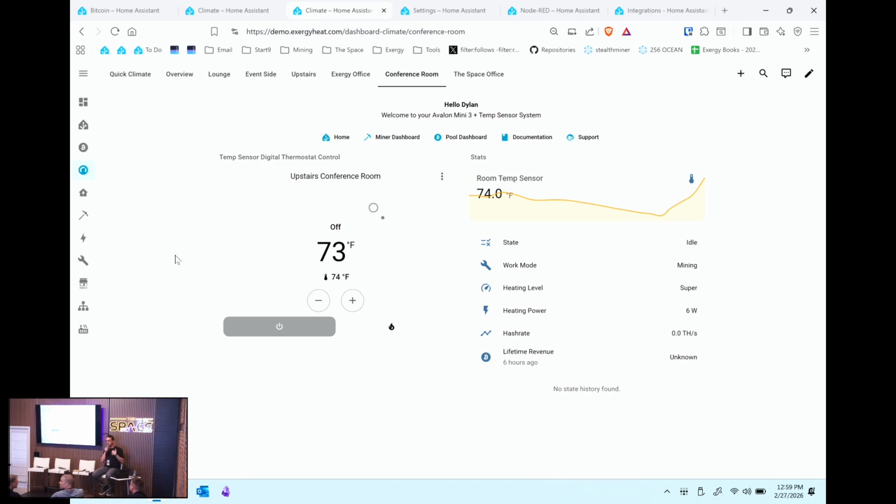Personally, I like to move away from Wi-Fi connected stuff, because if your router goes down at home for whatever reason, your Home Assistant can still be up and talk to all your Zigbee stuff and not be reliant on your local internet. Now, it might be difficult to talk to the Home Assistant itself, but at least everything can still talk to one another.